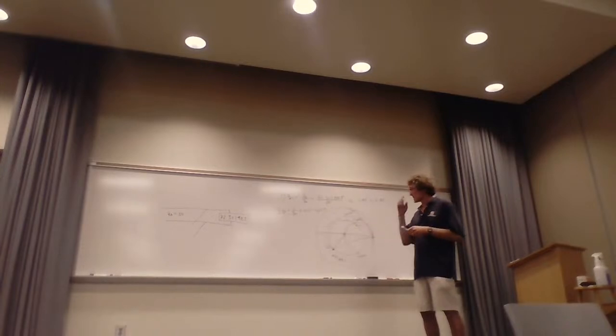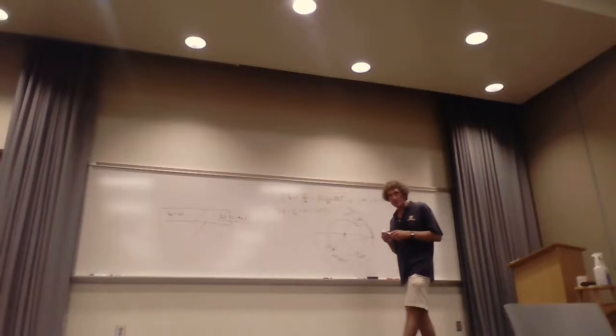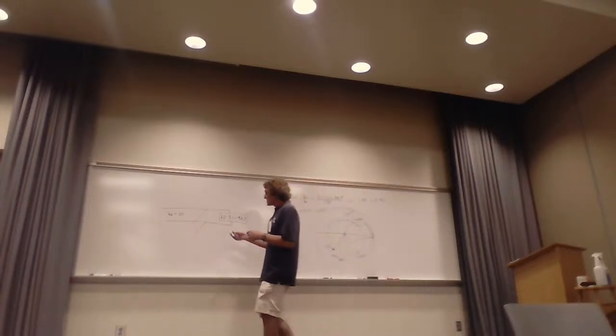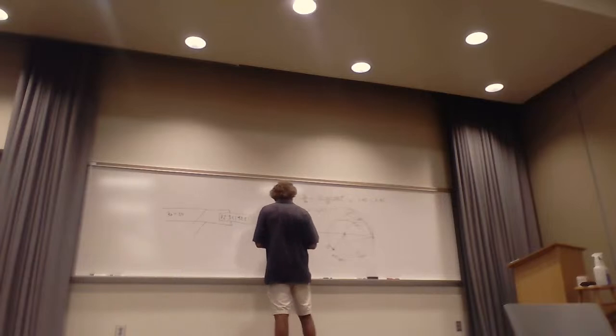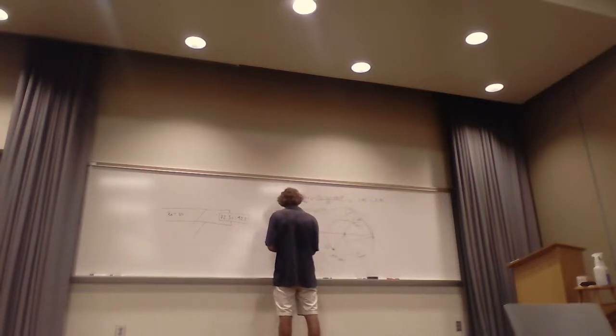Just watch this. Now, there are 2 possibilities. If it's open, I want you to just go with me on this. If this is an open circuit stub, what is the impedance of an open circuit? Infinite, right? Therefore, the admittance of an open circuit would be zero. It means you would start right here.